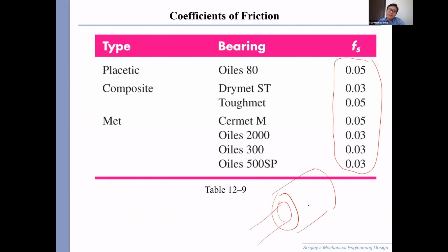If you get anything between the shaft and the bushing, it's going to be like sandpaper, okay? So if you have dust coming in between the shaft and the bushing, and remember, it's rubbing, if it's a high RPM, you rub a lot of this, and the dust literally becomes your abrasive, and you're going to wear out the bushing very fast.